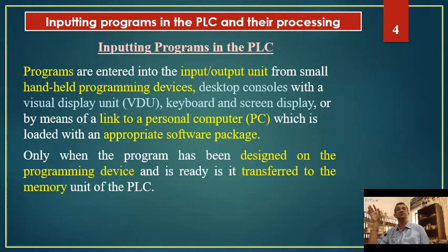So once it is transferred to the PLC, then the USB connection between the PLC and the PC is not needed, because the compiled program is already transferred and it is retained in the RAM or ROM section, the read-only memory section, of a PLC. So once that has been transferred, there is no further problem. But often we have to make use of a programming device in order to write a program for a PLC, and then once it is ready, it is transferred to the memory unit of the PLC.